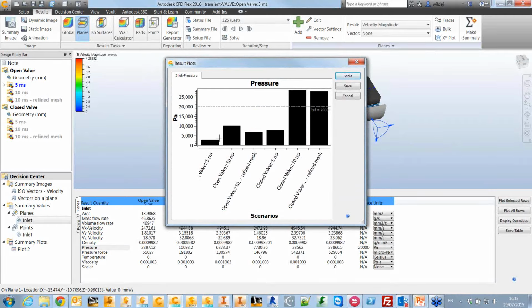So this is the pressure drop that I'll have through my system with the flow rate that I've applied versus my reference, of course. So I've got 3 conditions that are okay. But if I have a nearly closed valve with 10 meters a second, I actually need a higher pressure to drive the flow through the model than I have. So that design is essentially a failure.